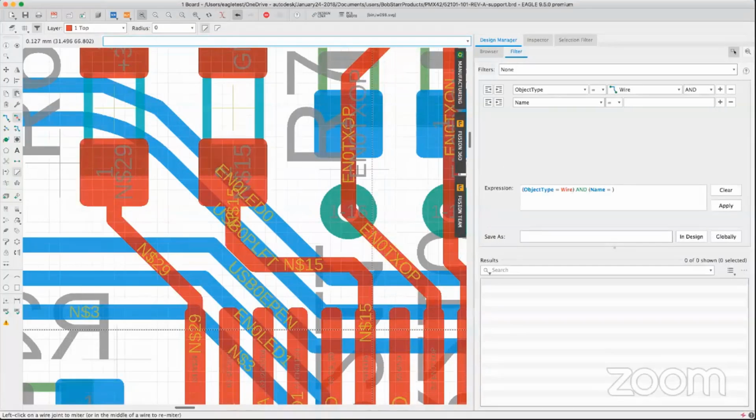Got any YouTube questions? Yeah, I think I got one here. Are rounded corners available as a library option on EAGLE? Not really sure exactly what you're asking there. Are you saying for the pads, for the SMD pads? Hello there. How to see the pad rounded corner? Well, when it comes to SMD pads, we do have the capability of having rounded corners. Yeah, and that's actually done by a percentage. So yes, you can have surface mounted pads with rounded corners. Okay, so for SMDs we do have that.